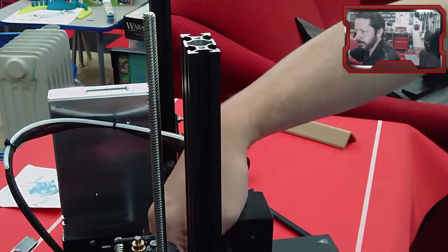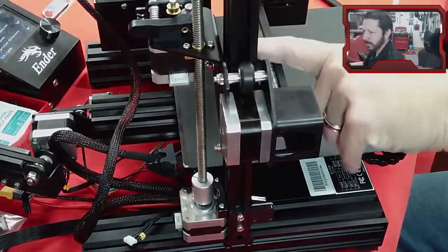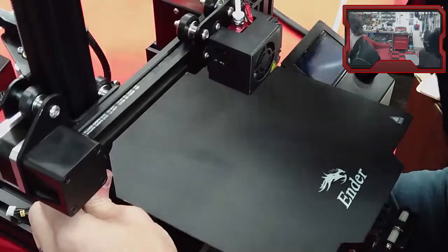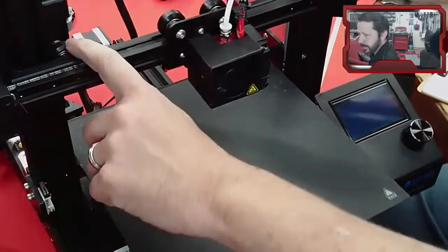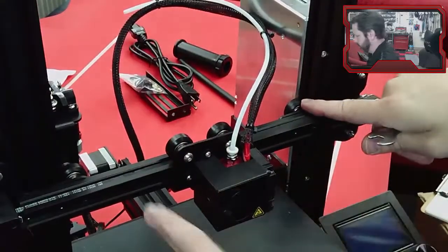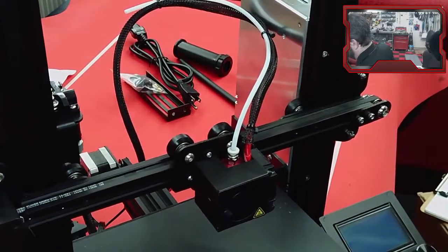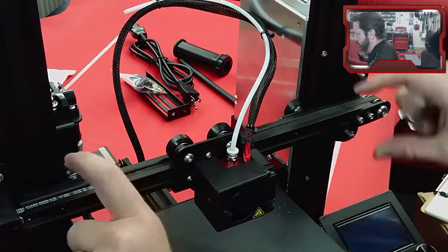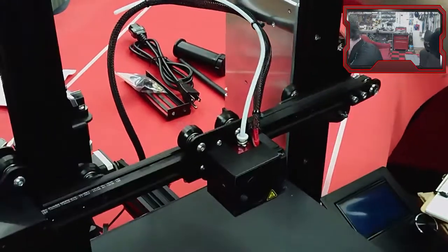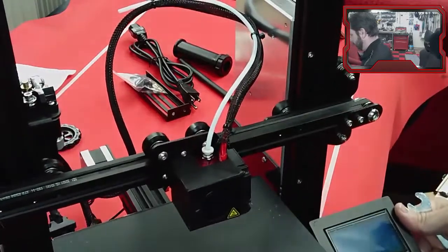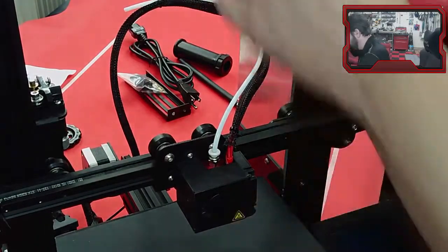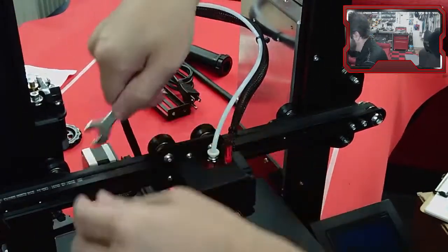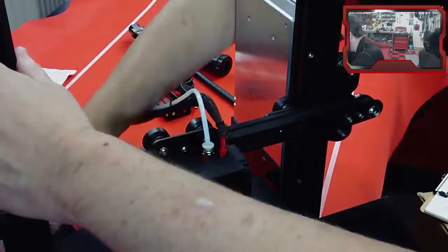What I'm doing, well, now I'm going off the screen again. What I'm doing is I'm adjusting these two. Let's see if I can get it facing you better. I'm adjusting these two eccentric nuts so that when I go up and down, notice how this side's moving and this one's not. I'm trying to get them to where they more or less move at the same time, because you don't want it doing one side moving a little before the other as much as possible. So it's going to take some adjusting on getting these nuts the right tension.